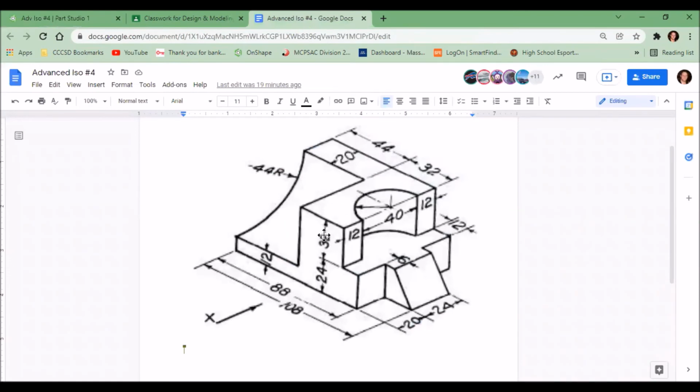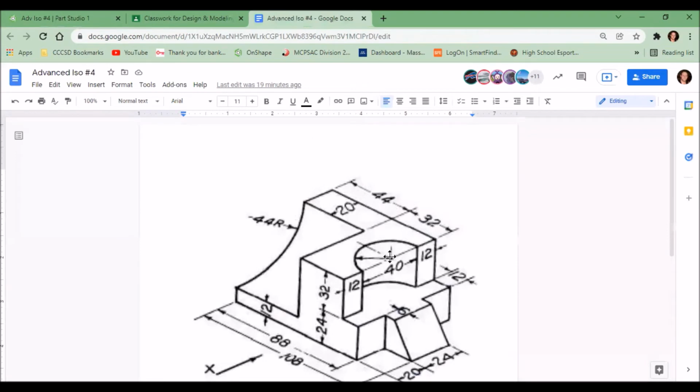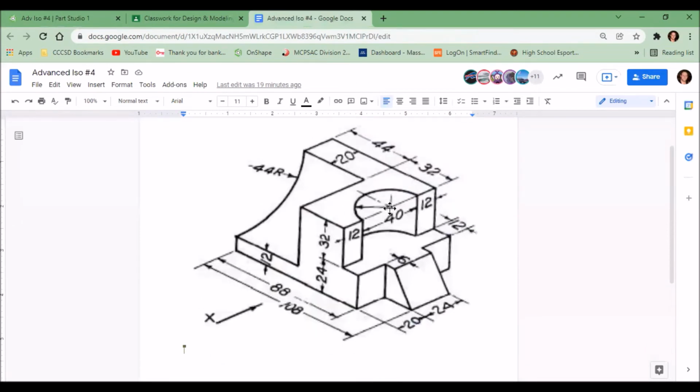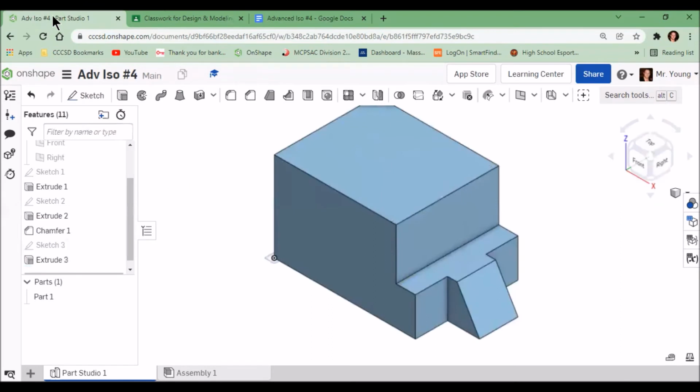2 more steps, and we've got this entire block finished. The one I'm going to do first is removing the small circle from the right side of our new block. To do this, I have to establish a circle on a sketch plane that is on top of the new block and centered up and down on the right line. Let me show you how to do that.